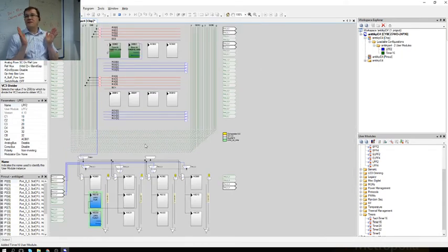So fundamentally that's all you need to do to make the low pass filter run. Plus, in the software, in order for that module to run, you must start it. But not only this module, you also need to start the timer module that gives the clock signal for that one. And not only those, but you need a programmable gain amplifier there.